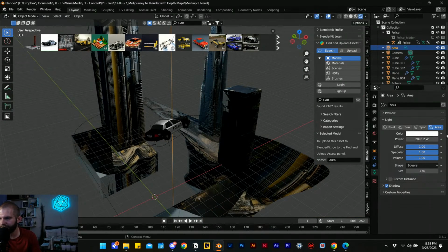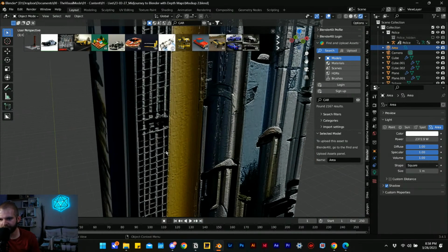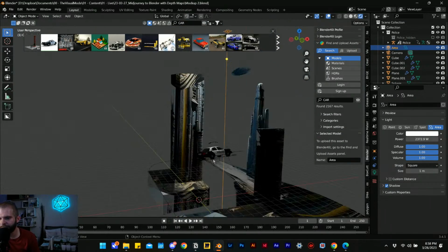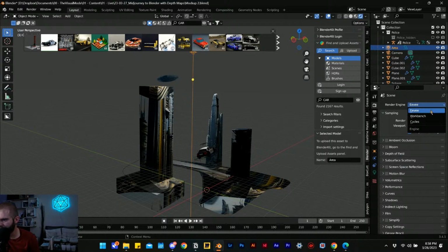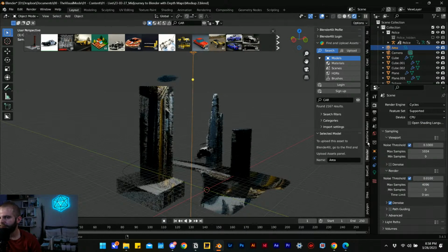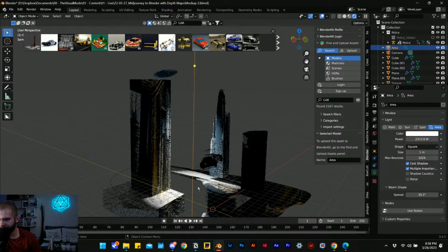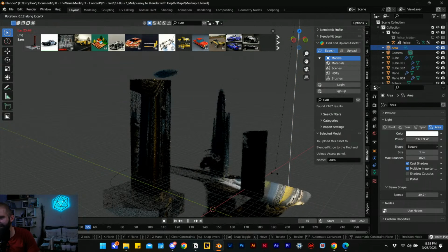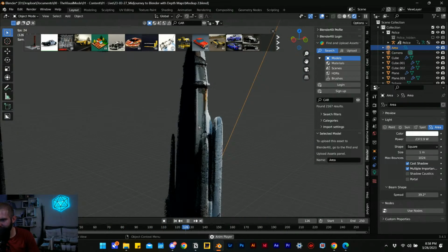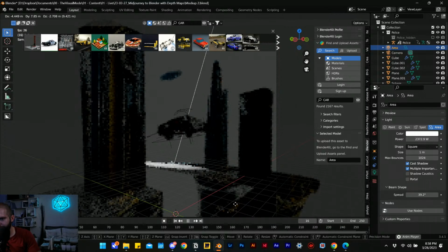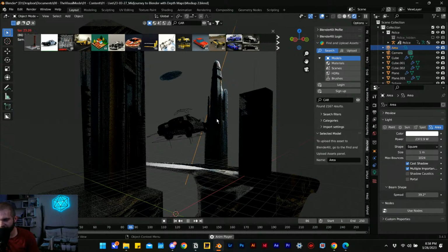because there are sort of shadows, unless the lighting is really soft from the AI generated image, where you're basically only getting ambient occlusion, you're only getting these soft edges in between different surfaces, then you can get away with doing, switch over to Cycles, then you can get away with doing really harsh shadows. So we go over to the light properties and we turn down the spread. So it's basically like a spotlight, or we make it a sun, right? And if you start to get these really harsh shadows on something that's soft lit, right, you can basically use it as a 3D scene.